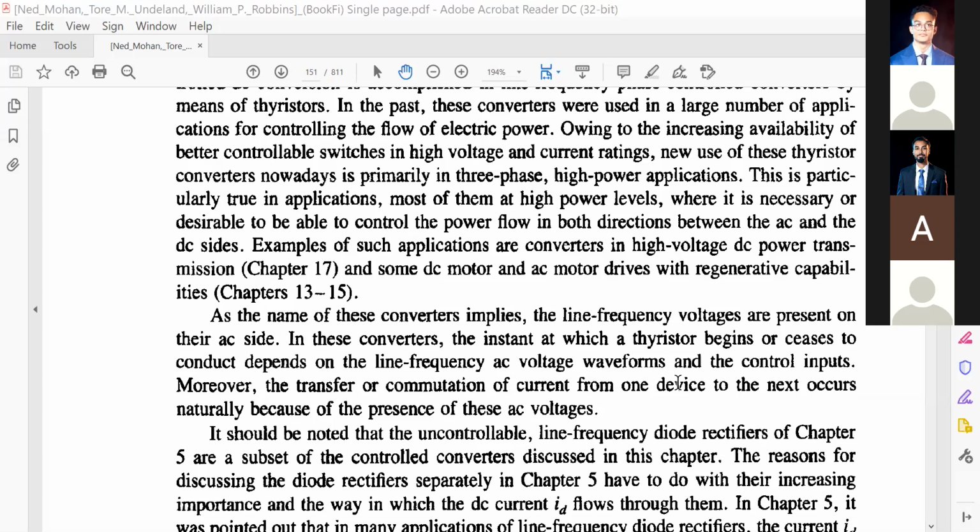So in the video, it is mentioned how you want to stop conducting the thyristors. They mentioned that you can use an LC oscillator in conjunction with the DC, and if you add this AC with this DC, and if this LC peak value is greater than the DC voltage you have applied to the thyristor, then you will have a reverse bias.